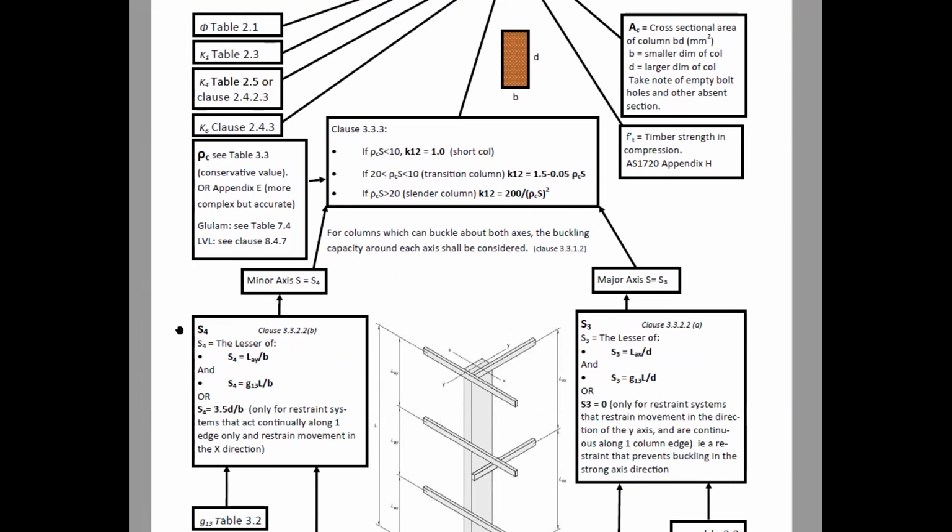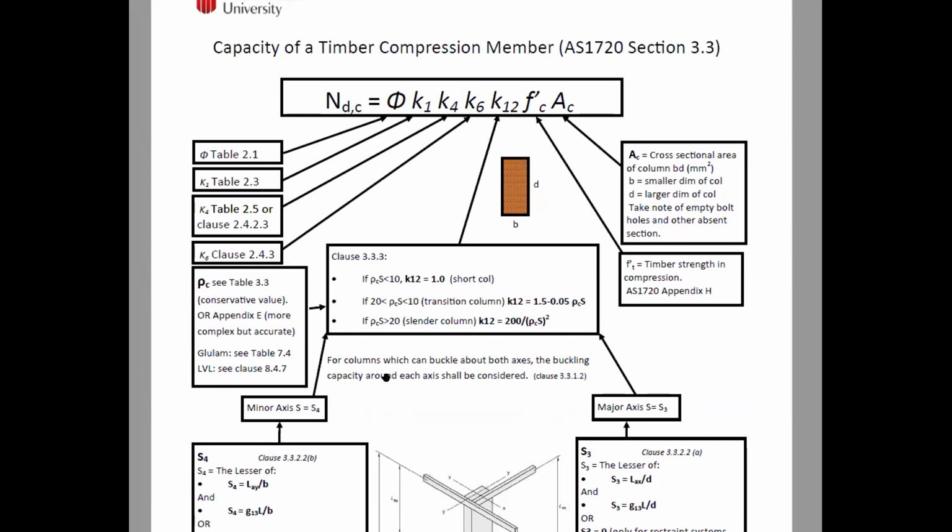And since that's individual, we'd only use 1 for K9, and for K12, that would be substantially restrained because it's evenly spread across the top of the beam. The only difference is the FC value. FC in compression, parallel to grain versus perpendicular to grain, they're different values. And sometimes they don't give a value for perpendicular to grain. I'll review that with you as well.